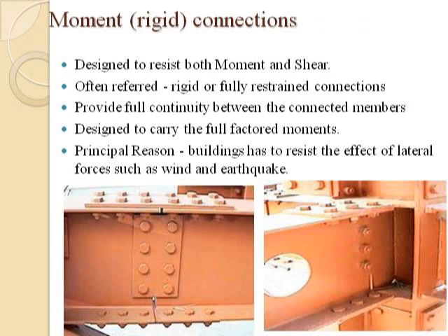Secondly, we have moment connections. These are designed to resist both moment and shear. A shear connection won't resist moment, but moment connections will resist both moment and shear. These are often referred to as rigid or fully restrained connections. We can call the moment connections rigid or fully restrained connections also.